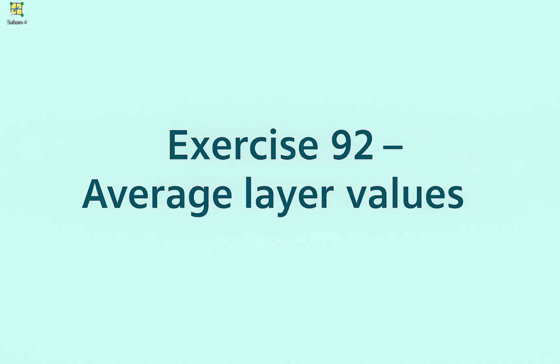variables. In this case, we are going to create a thickness and a porosity that will use a cutoff value of 15%. So we will not overwrite the petrophysical data that has been imported previously as petrophysical data for the wells for each layer and well combination, but what we will do is create new variables that we will call hk15, referring to the thickness with the cutoff, and phi 15, referring to the porosity also with the cutoff